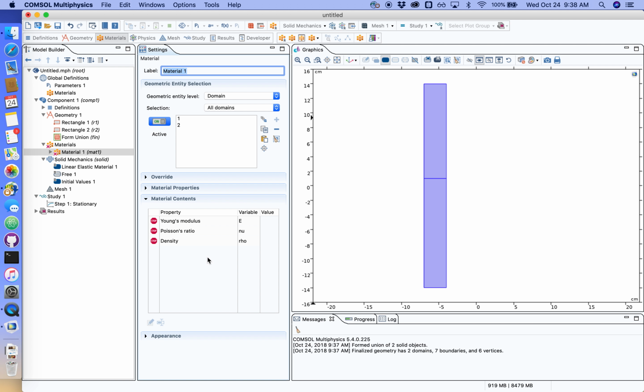So if you want to do this, just Googling the material that you're interested in simulating and then Young's modulus or Poisson's ratio or density, you can very easily find ballpark values for whatever material you're trying to simulate. Now it doesn't matter if it's exactly the same material. For example, in lecture I was simulating a blood vessel wall, but I used material properties from rubber. That's close enough, right, for the purposes that we're studying in this class. So we defined Young's modulus and Poisson's ratio in lecture, and so you know what those mean.